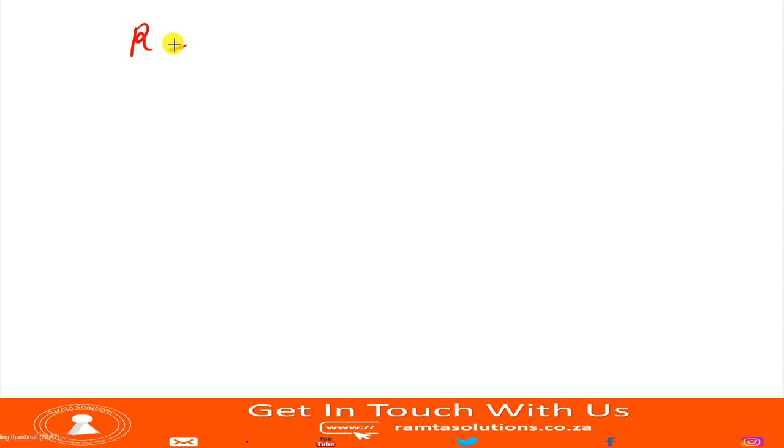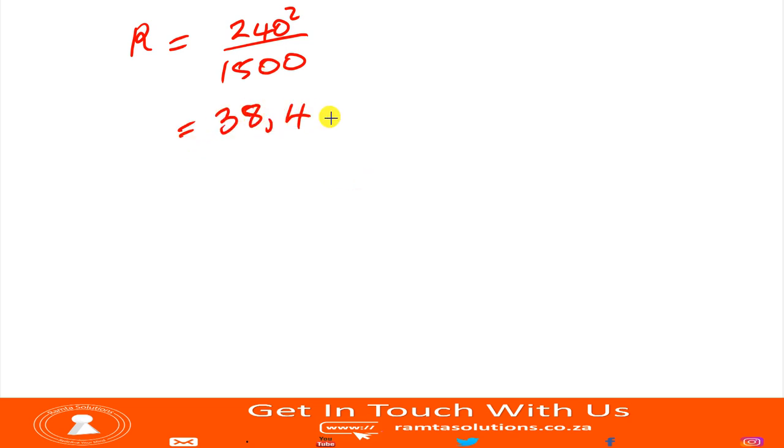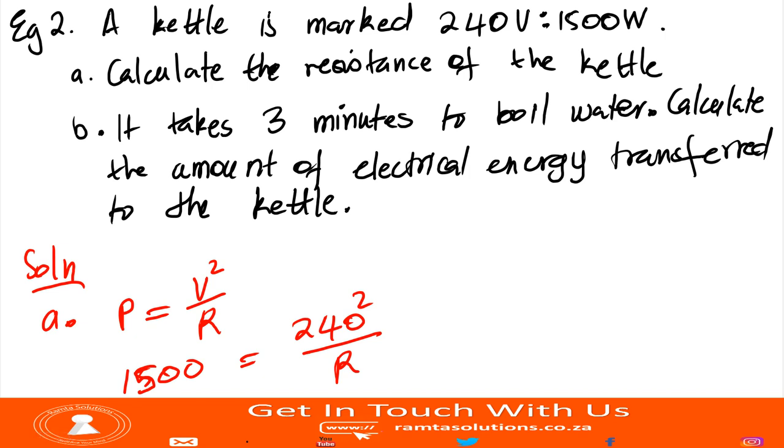This means R equals 240 squared over 1,500. So this is 38.4 ohms. All right. So the resistance of this kettle is 38.4 ohms. Remember those formulas that we were deriving. Now we're using them. How nice. Very nice, eh?